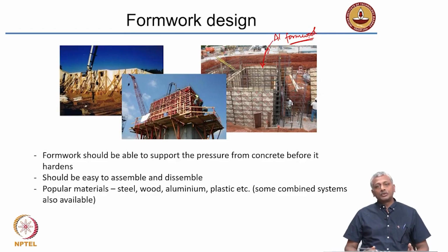So today you don't find that you have framed structures with infill walls made of masonry. Mostly you will find in multi-storied buildings that you have framed structures with walls also which are reinforced concrete. Okay. So it's totally different. The kind of construction today for multi-storied buildings has become quite different as compared to what was there maybe even 5 to 10 years ago.